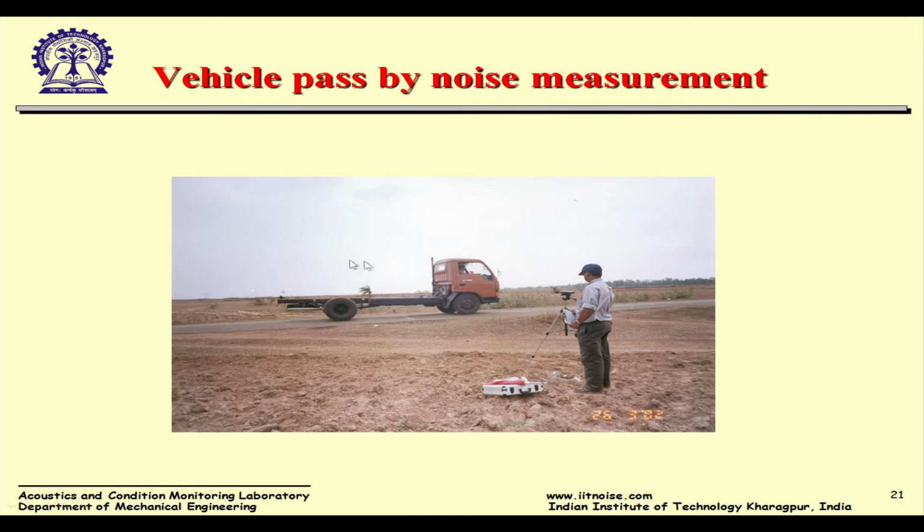And this is the same location. Once we put some noise control measures in place, we again do the noise source pass-by noise measurement, on a tripod 7.5 meters far away. Fortunately in Kharagpur, we are located between two defense establishments. They have a road which is not used by anybody, and sometimes I sneak in my vehicles for pass-by noise, of course with their permission, and they allow me to do that.